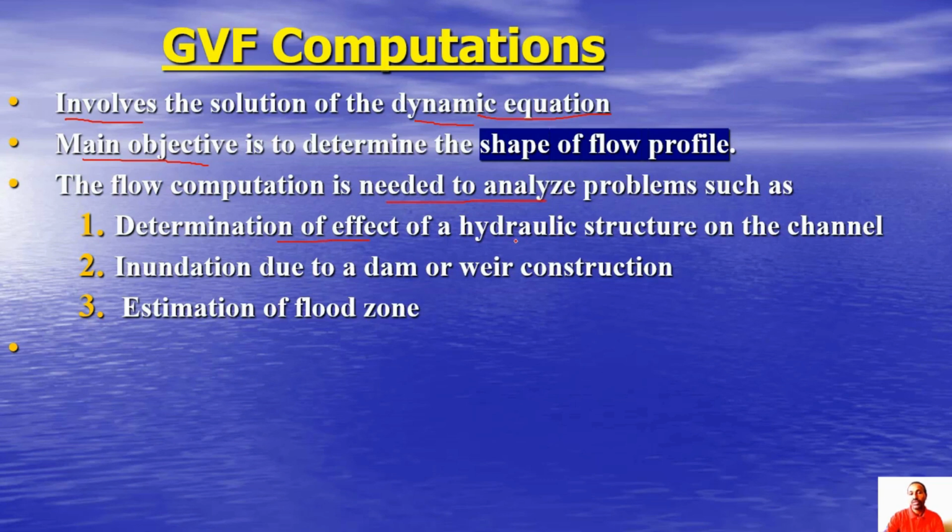Flood may overtop the bank of the channel, which can create erosion on the side of the channel, or sometimes damage to the structure. We will also determine inundation due to a dam or weir construction. This is another aspect of why we do GVF computations.